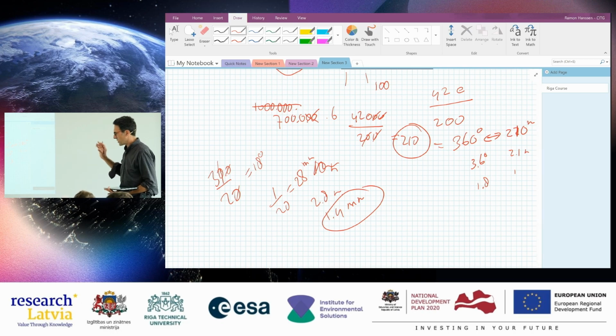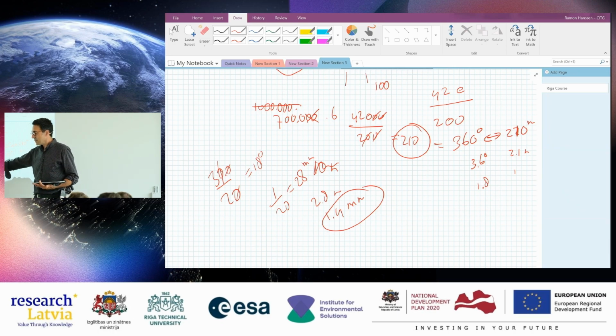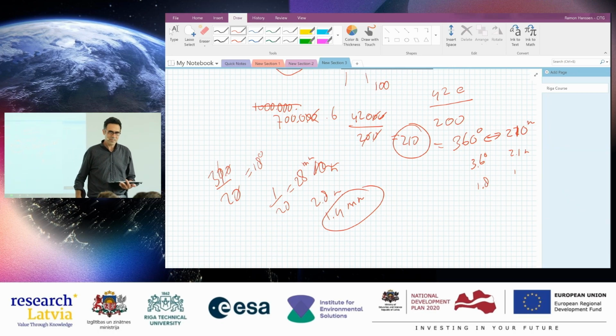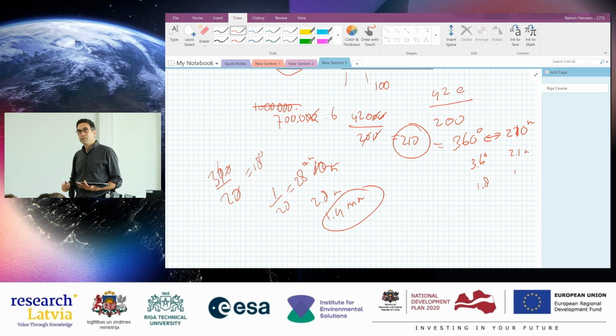Right, so this already, I told you the sensitivity to deformation is 1,000 times better than for topography. So basically, SRTM is good enough, right? If we have a laser scanning DEM for Latvia, great, we'll use it. But when I did this processing, or asked somebody to do this for me for Latvia, we didn't have an elevation model, so we just use SRTM. And so if there are errors, it would be something like this, if there's a 10 meter error. And I don't think there's a 10 meter error in SRTM. Yep. You had another question?